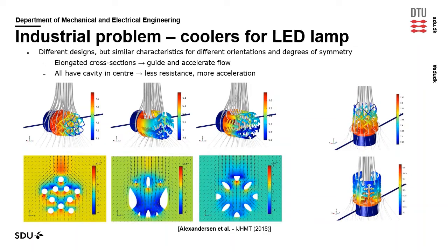If we look at the pressure fields, again for a cross section, we see, of course, as we would expect for the lattice designs, we get a lot of stagnation pressure regions. So we have a very high fluid resistance because the fluid keeps moving and then hitting these many features.